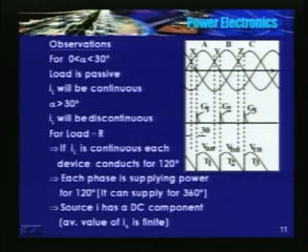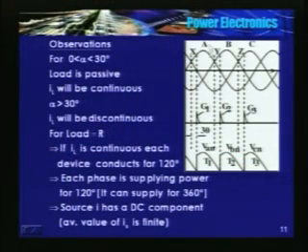It continues to conduct beyond X because we have not triggered T1. Till you trigger T1, T3 continues to conduct. Till you trigger T2, T1 continues to conduct. So the instantaneous value of load voltage is VCN. See, this is VCN at alpha equal to 30 degrees, plus T1 is triggered.